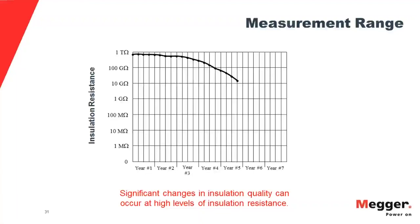And it's still very high, and a single test would make it look like, oh, this is good. You wouldn't have any problem determining whether it's good or bad, but you wouldn't have any idea of the rate of change. What may be happening here, if this was a motor in an industrial environment, let's say, is that there could be moisture getting from a nearby process, and all you may need to do is put up some sort of a guard around it, and you could stop this. Okay.